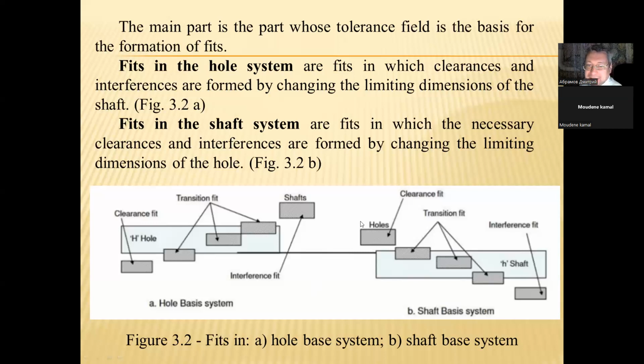Fits in the shaft system are fits in which the necessary clearances and interferences are formed by changing the limiting dimensions of the hole. The tolerance field of the shaft is constant, and we change the tolerance fields of the holes.